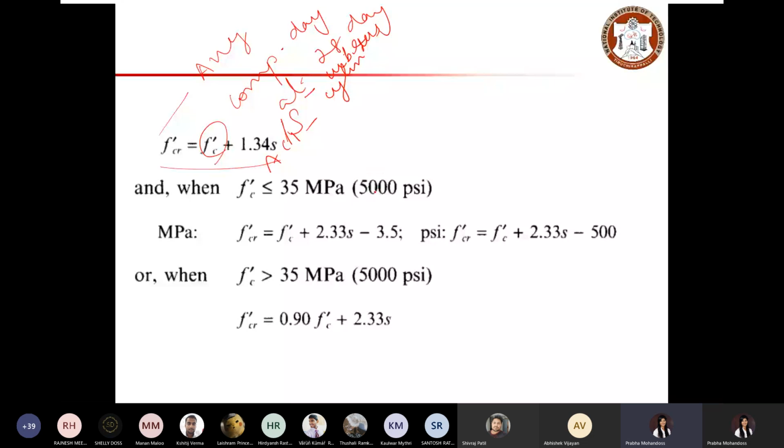So the compressive strength depends on the geometry of the specimen also. This in detail we will discuss when we discuss testing and the hardened properties of concrete. But here, to get the basic difference, you should know what the compressive strength of a cylindrical specimen will be about.